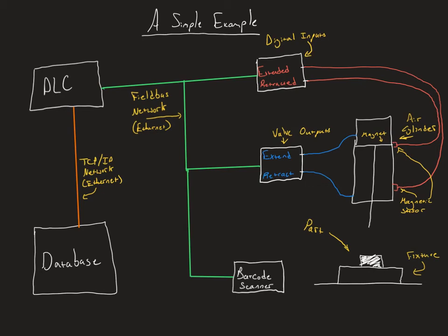So we have the following loop to be able to command the PLC and get feedback on the actions the PLC requires. Based on the basic idea we presented earlier, the PLC generates outputs, which then cause an actuator to perform some action, which then causes a change in the real world, so it puts the cap on the pin, and the magnet comes down and is now in line with the magnetic sensor.